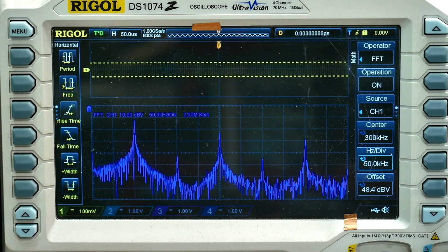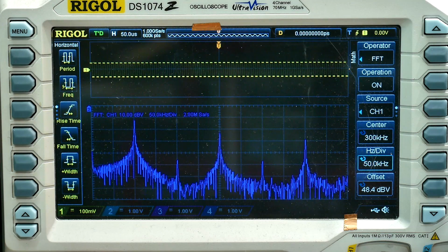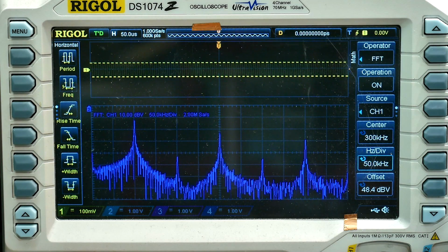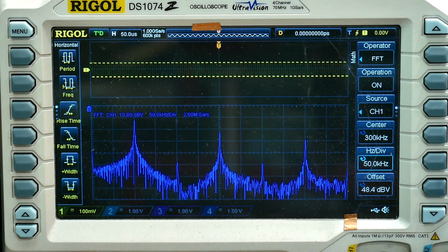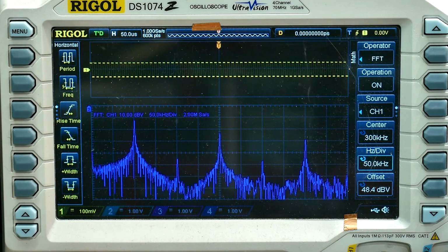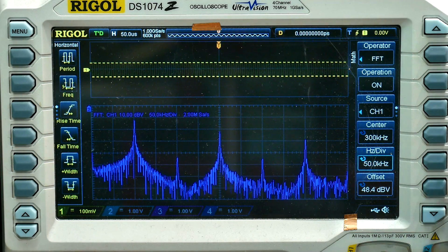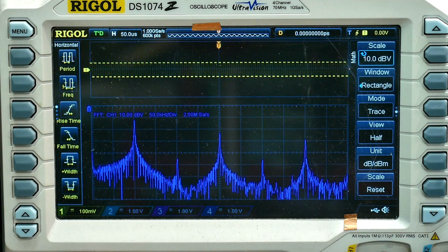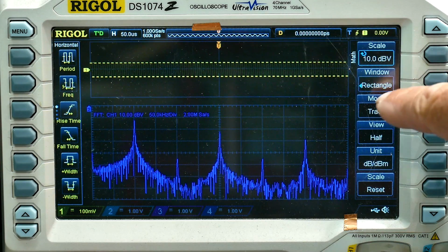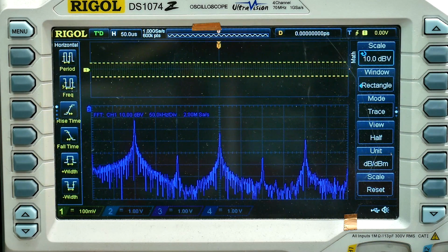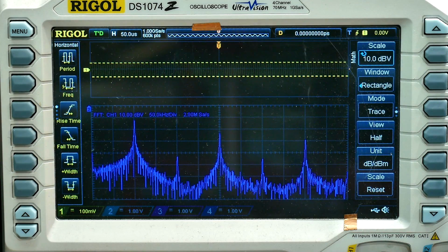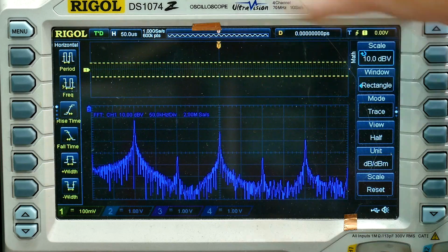Then you're going to say, well, that looks terrible. What's all that noise, and why aren't these nice shapes? Now remember, on the spectrum analyzer we played with resolution bandwidth. Well, we need to play with something different over here. It's not resolution bandwidth. To get there, we're going to window down again, and that was a Freudian slip. So we're going to look at the window function. Okay, so what is a window? We have window, and it says rectangle. You go, oh great, we're looking at a rectangular window, and maybe I can set that to a square. No.